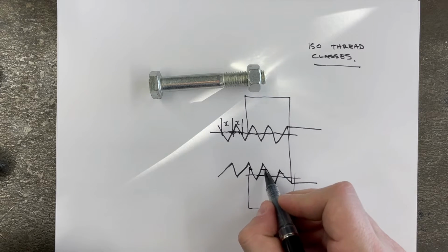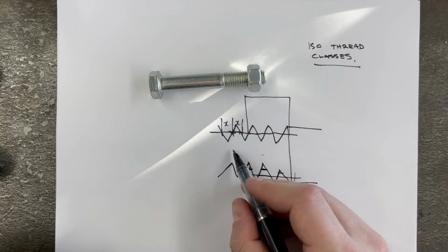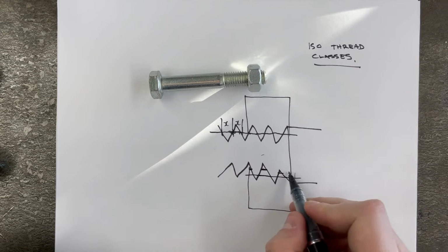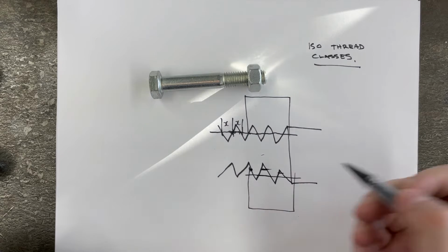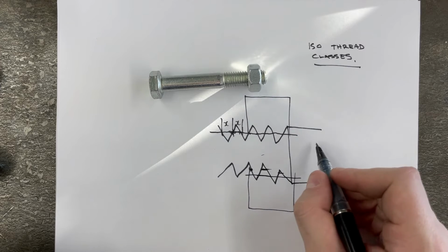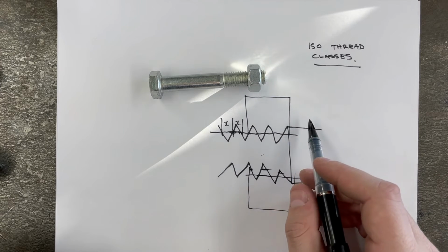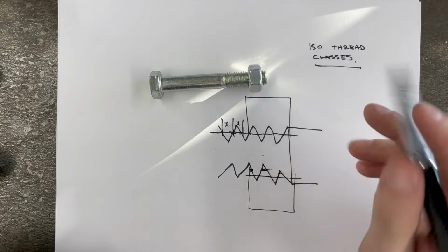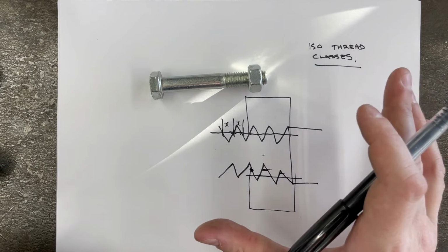So it would be the minor diameter on the class A thread, but it's the major diameter on the nut. And basically they look at that, and then they factor that in for the absolute fundamental deviation from what would be considered the standard. So I'm not going to get into all of it. That's something that you'd have to reference in a book.